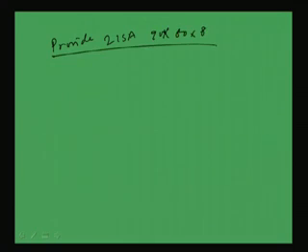So, the effective length is not going to reduce, the slenderness ratio is not going to reduce, the allowable stress is less. As a result, the sectional properties have to be more, the dimension and cross sectional area have to be more to carry that much load. So, we can provide 2 ISA 90 by 60 by 8.